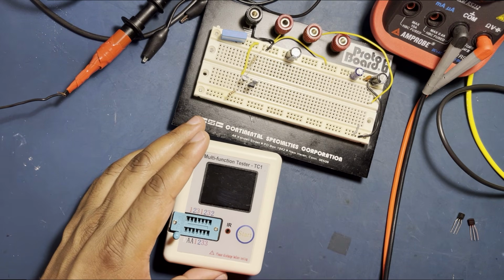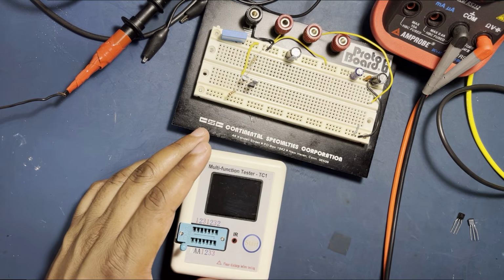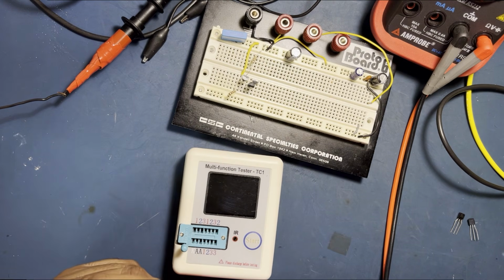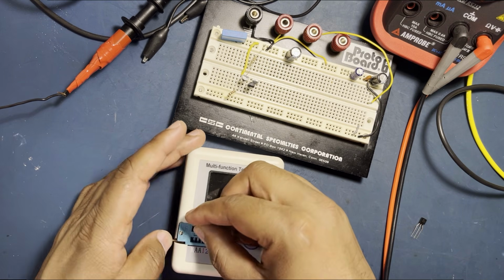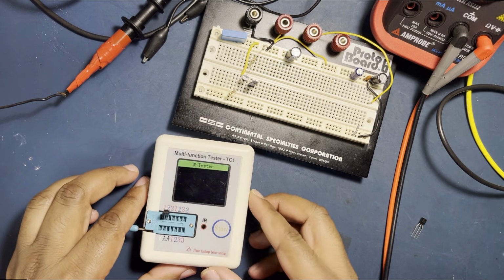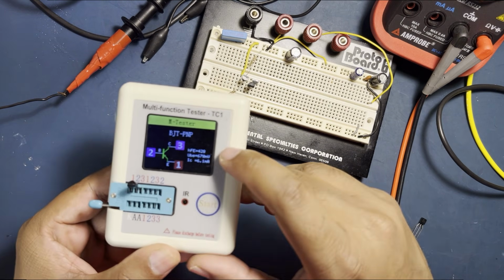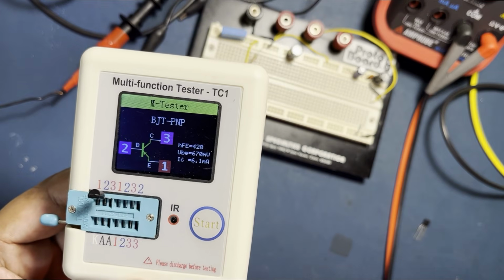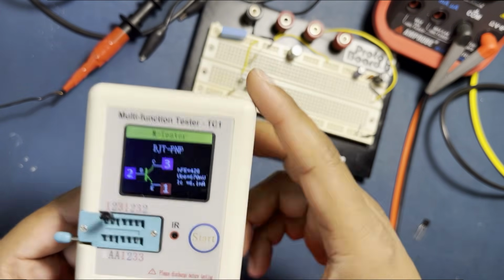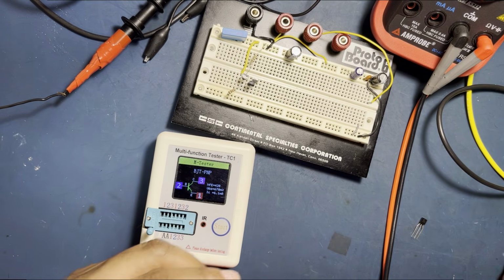Okay, I just want to quickly show you the transistors that I'm using. For most of these transistors, we assumed a beta of 100, right? So we were designing them for that, but they're actually a lot better. If I grab one of the PNP transistors I'm using and use this tester real quick, you can see the beta on this is, I don't know if it's going to focus, 428, so it's much better than what we assumed for our design.